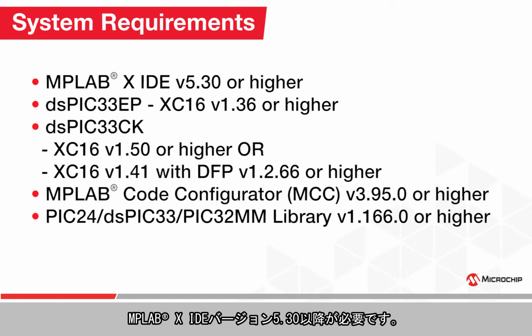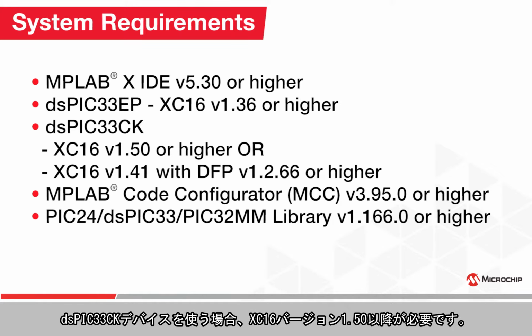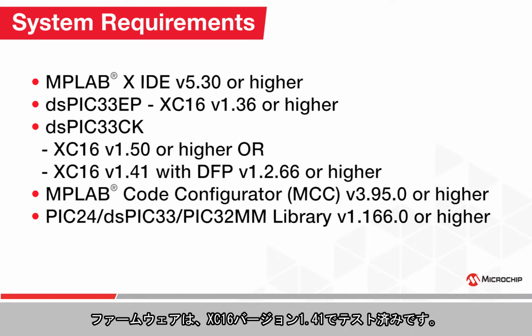You should be running MPLAB-X IDE version 5.30 or later. If you are using a dsPIC33 EP device, you should use the XC16 compiler with version 1.36 or higher. If you're using a dsPIC33 CK device, then you should either use XC16 version 1.50 or later, or you should use XC16 version 1.41 with a device family pack, version 1.2.66 or later. The firmware itself has been tested with XC16 version 1.41.